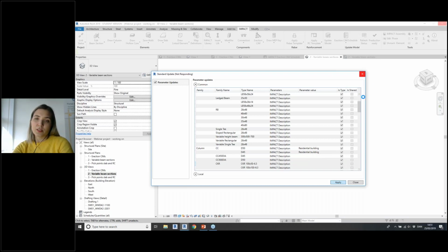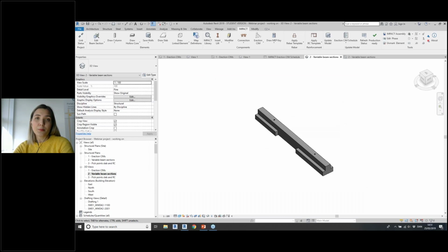This column is basically general information, which tells the user if it is a type or shared parameter. While working in Revit, it is important to differentiate those parameters, because type is something that is only used for the family, and shared is saved in your shared file as an external file, which you probably receive from us, impact shared files, and you add your own shared parameters. And shared parameters can be used in tags and schedules.